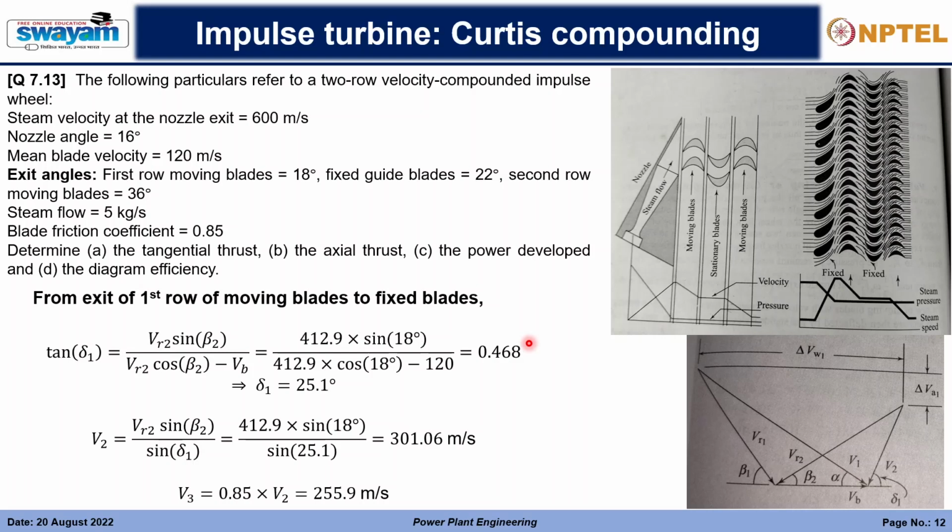You're right, right. But what is the condition now? The steam is now moving from this moving blade to the fixed blade. So this blade is not moving, right? So whatever steam is inlet, what is the velocity of this? 0, right? So we need not subtract anything from the inlet velocity. Here the blade was moving, so we have to consider its velocity to calculate the relative velocity.